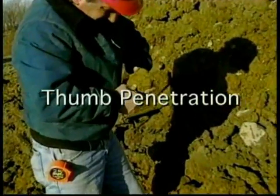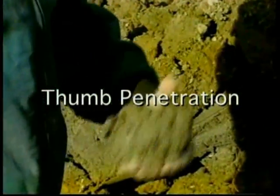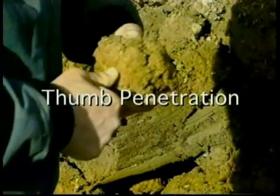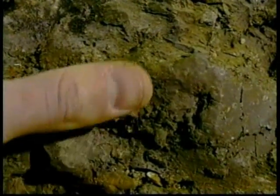In the thumb penetration test, you determine how difficult it is to push your thumb into a large clump of freshly excavated soil. Type A soils will be only slightly indented under pressure. If only moderate effort makes a dent, that could be type B soil. Type C soil is easily indented.